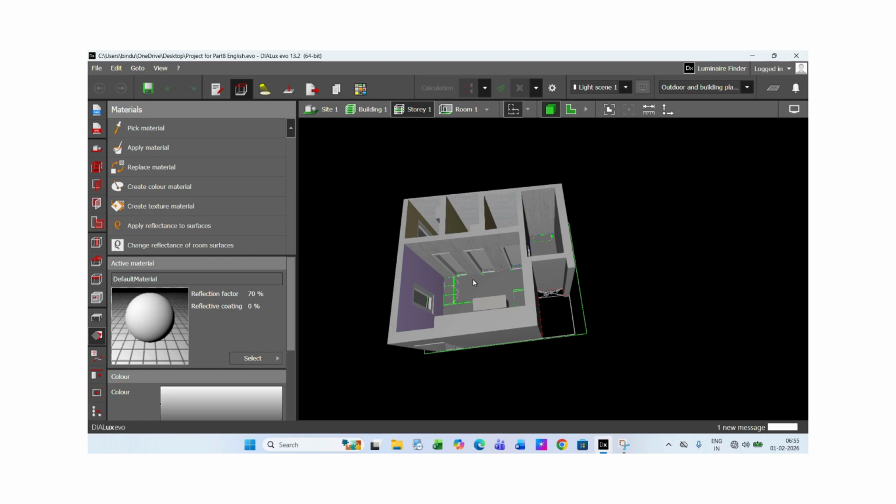If it's an engineering drawing board, and you are making a drawing on paper, you need a standard lux of 500. This 500 lux should be on the working plane, meaning on the drawing board.